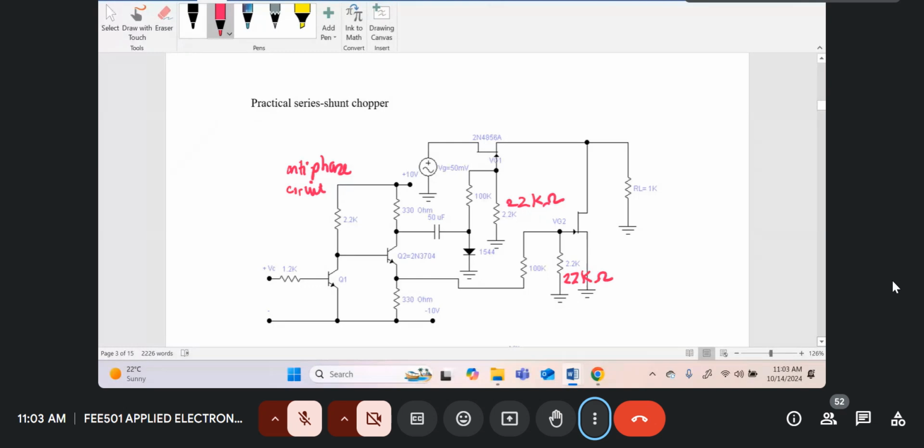So how does this circuit work? I'll just explain it very simply. The function of Q1 and Q2, these BJT transistors, is just to give two signals at the gates, VG1 for the top transistor and VG2, so that when the gate of the top transistor is going high, the gate of the second transistor is going low. I.e., when the top transistor is on, the bottom transistor is off, and vice versa.